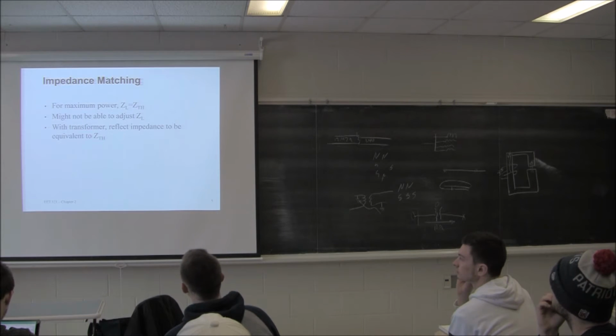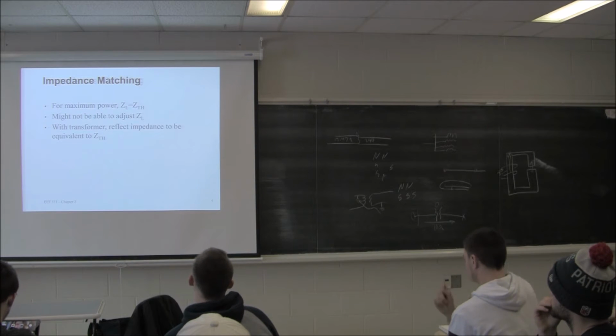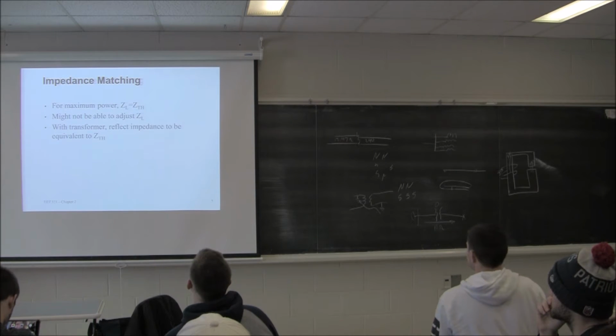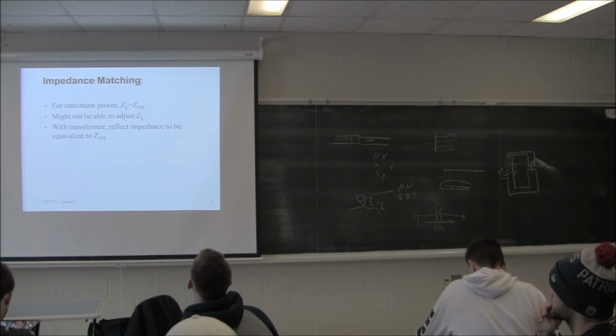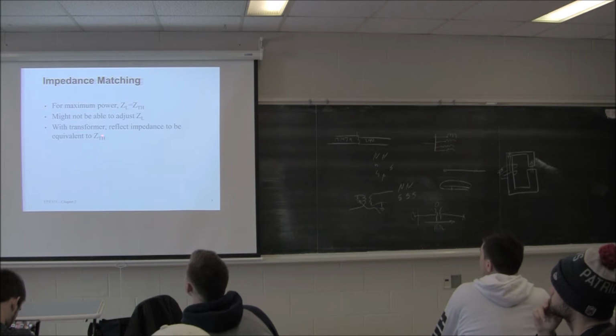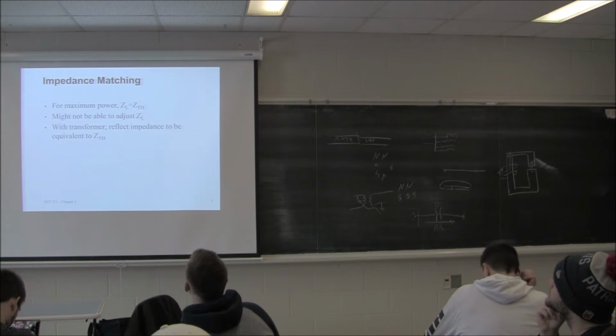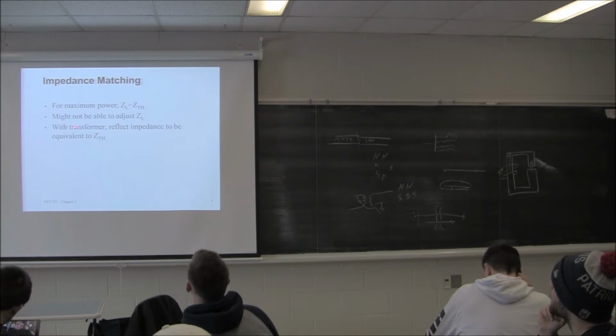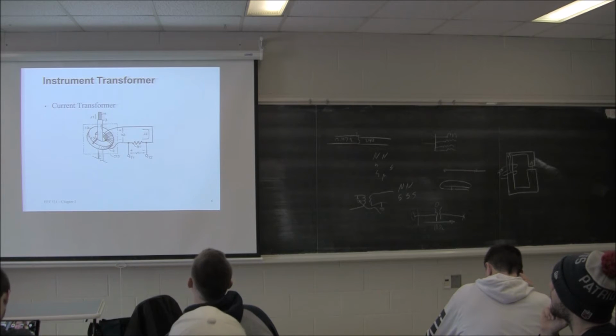We talked about this for max power transfer, ZL equals ZTH. If you buy the speakers, usually you can't change the impedance on speakers, at least that I'm aware of. Maybe you can, but I don't know anybody. So you have to be able to reflect the impedance from the load to the source to match it up.